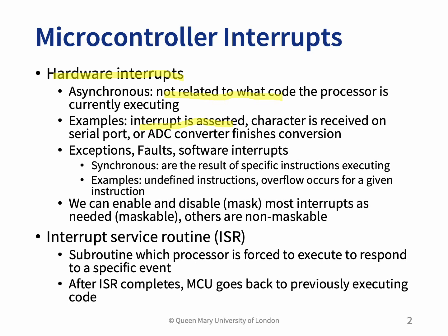The next one I'd like to talk about is the exception faults for the software interrupts. For the software interrupt, the behavior is synchronous because it is the result of specific instructions executing. It can be, for example, undefined instructions, or overflow instructions that occur for a given instruction.